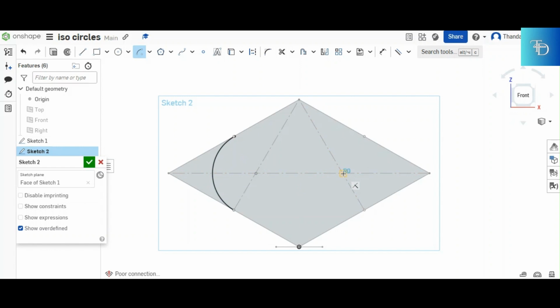You come to the opposite center, you open your compass to the center, you do the same thing. Now you place your compass here, you open it up to the opposite point. You join what's remaining of the arcs. You come to the bottom, you place it there, you close everything up like this. And ladies and gentlemen, this is how you draw an isometric circle.